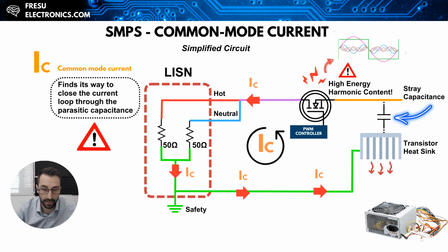As a second possibility, we can use a thicker washer, which will reduce the capacitance. And the third option is to leave the heatsink floating. But in this case, we have to ensure that the user has no access to the heatsink and cannot touch it. Otherwise, this can create a shock hazard for the user.